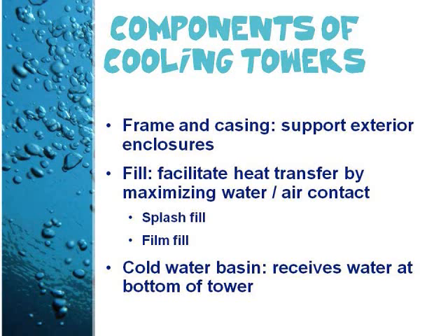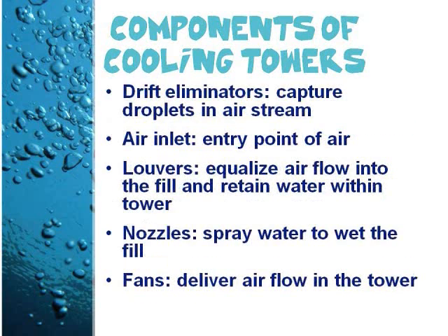Propeller fans are mounted beneath the fill to blow air up through the tower. With this design, the tower is mounted on legs, providing easy access to the fans and their motors. Drift eliminators capture water droplets entrapped in the airstream that otherwise would be lost to the atmosphere.